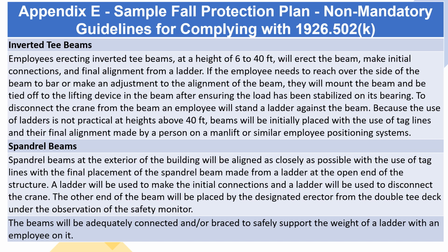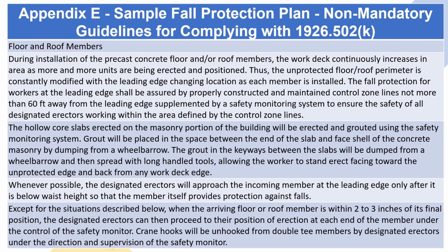The other end of the beam will be placed by the designated erector from the double T deck under the observation of the safety monitor. The beams will be adequately connected and/or braced to safely support the weight of a ladder with an employee on it. Floor and roof members.